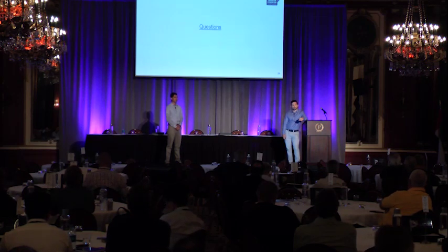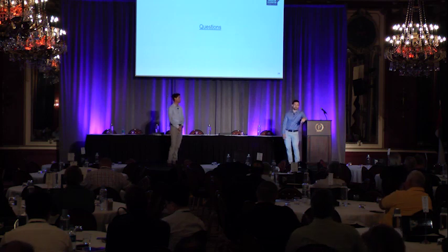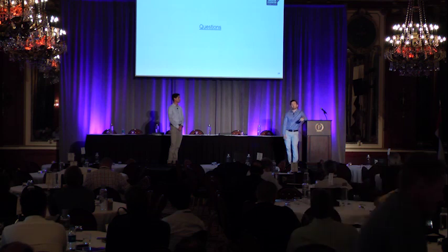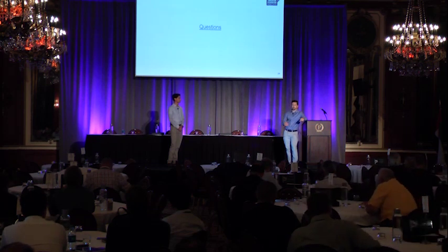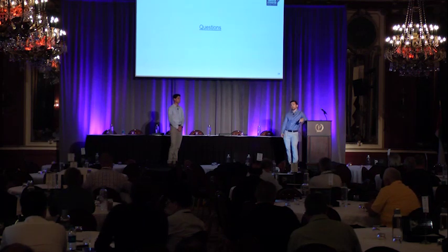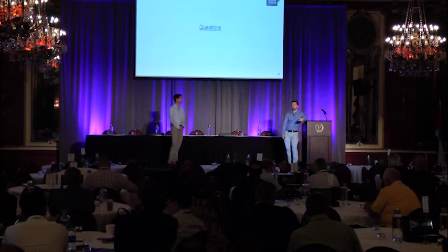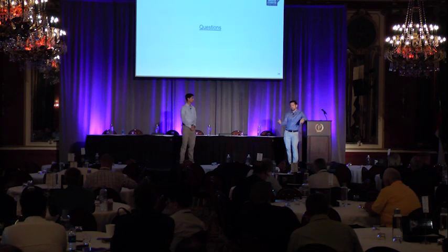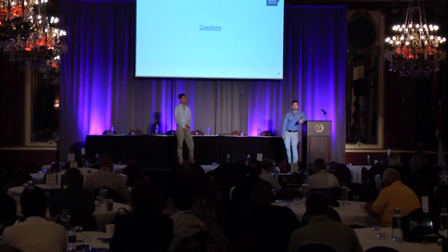Correct. They were. Yeah, so typically the 3-foot wide, 6'4" walk-through frames or 6'8" walk-through frames can support loads from 12 to 20,000 pounds. In that case, it was just a couple steel beams and a timber roof, so the loads were very light. In that case, the general contractor called and said our scaffold system had failed, but when they went out and checked it out, there was a bunch of dents in the side of the system. It was obvious something had ran into it.